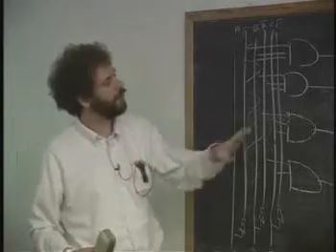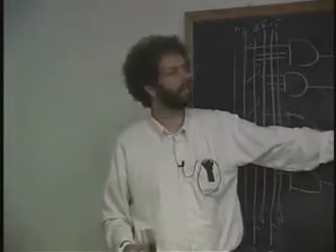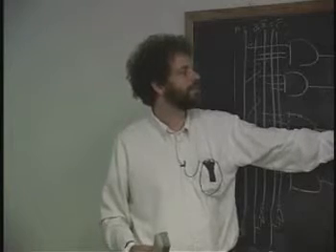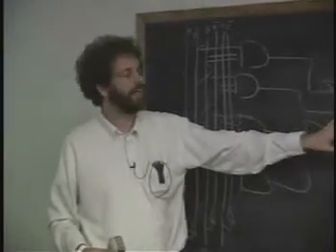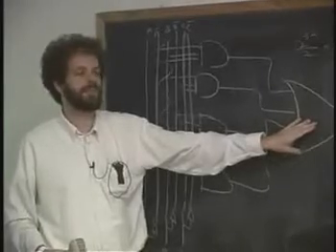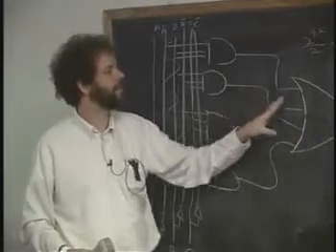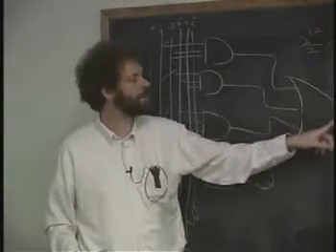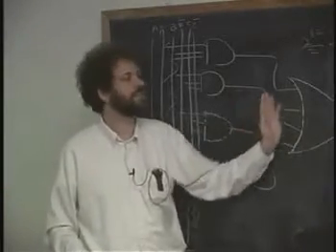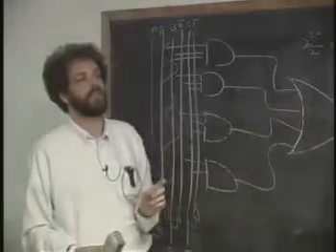Even worse than that, we have 2 to the 31 wires going into this big OR gate. So it's an OR gate with 2 to the 31 inputs. I've never seen an OR gate like that, but if there was one, it would be incredibly slow. Again, because it would have to consider all of these things, and in determining what the output should be, there would be a lot of charge that would have to get transferred to figure out whether one or more of these is in fact high.